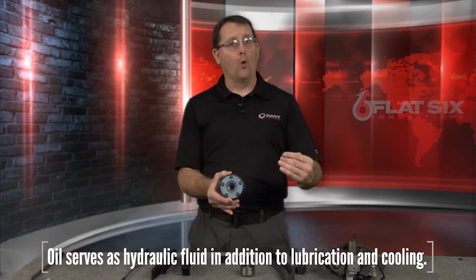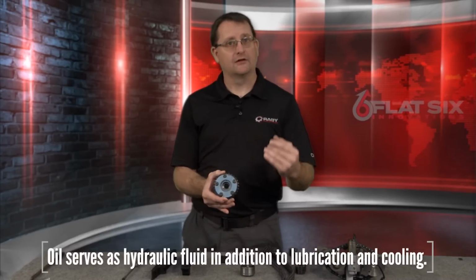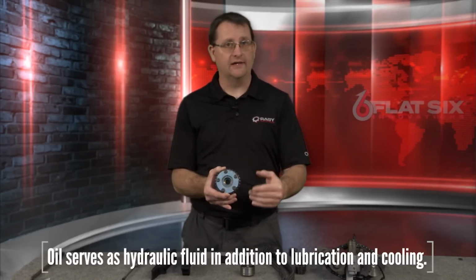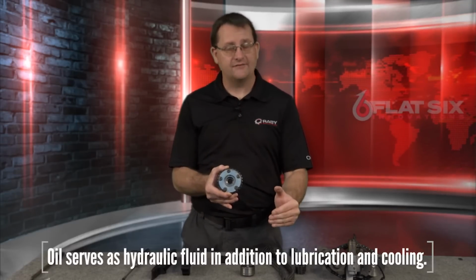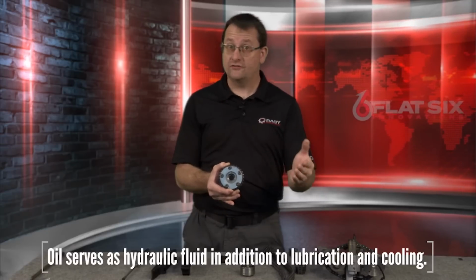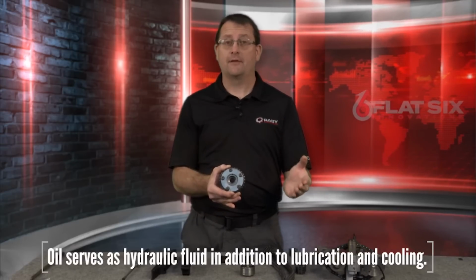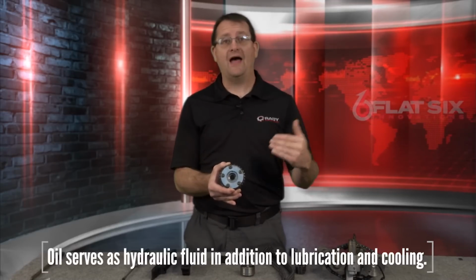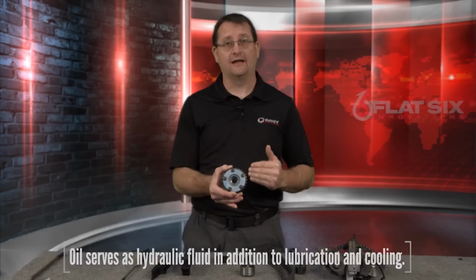We're going to talk more about oil and that sort of thing as we move on, because with these engines, your oil just isn't there to protect and lubricate and cool things. It's also used as a hydraulic fluid to change your variable valve timing, and in some of the later engines that have variable valve timing plus, it also controls the valve lift, how far your valves are opening on the intake side of the cylinder head.